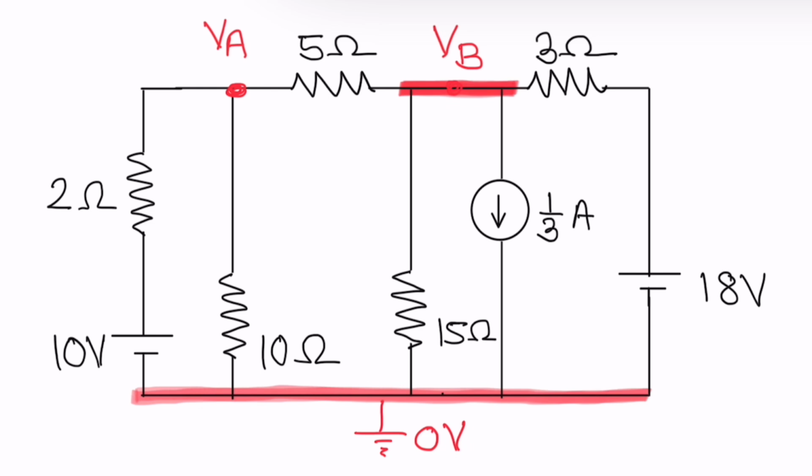So we have two nodes where equations are to be written, node A and node B. Let us see how many currents are at node A. We will write down the equation at node A, and when we do that, we assume all the currents are outgoing. So how many currents are there? I1, I2, I3. These are the three outgoing currents we will assume from node A. So how will the equation be? I1 plus I2 plus I3 equals 0.